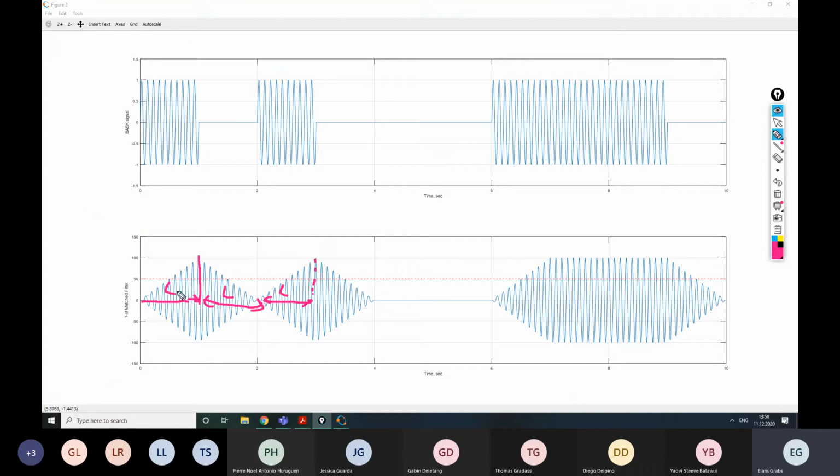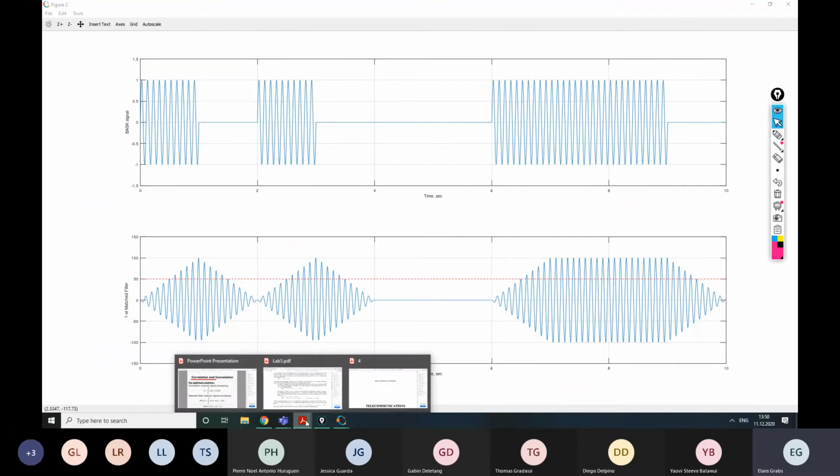And we need to sample it with a factor of L. So basically here we have something around 2000 points. So we need to read at the position 200, at the position 400, with a step of 200 and further, right? We start with L, go with the step of L, and in the same way proceed up to the end of the signal.